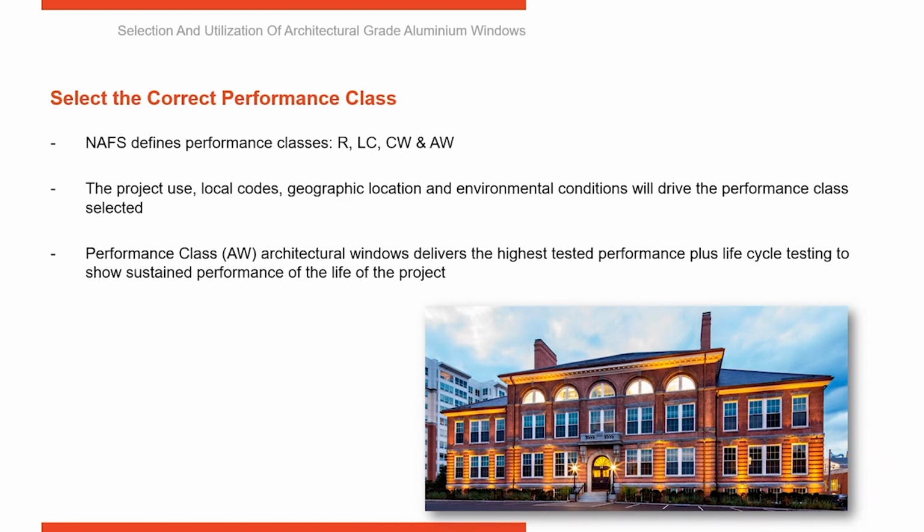When you're looking at AW windows, it brings in life cycle testing. So NAFS establishes your 4 performance classes, then AW, being the most strict and highest performing one, also brings in AAMA 910 for life cycle testing.